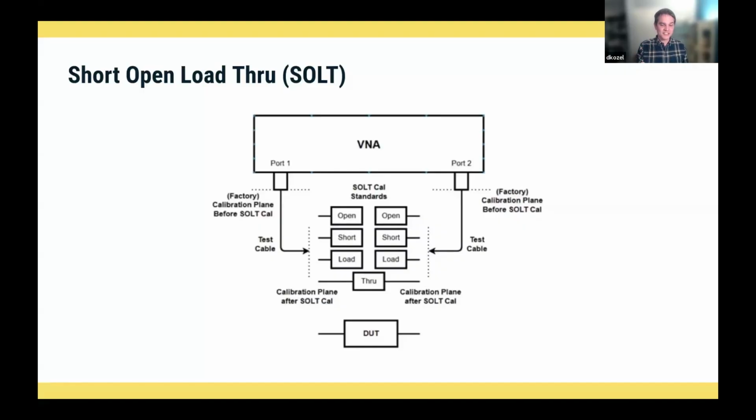What you'll inevitably see is that you attach this to an uncalibrated VNA, and it won't be a perfect point on the Smith chart, or it won't be a perfect 1-to-1 SWR. There won't be all the power going back. Some will come back, and the VNA measured that and said, oh, okay, this is my imperfection.